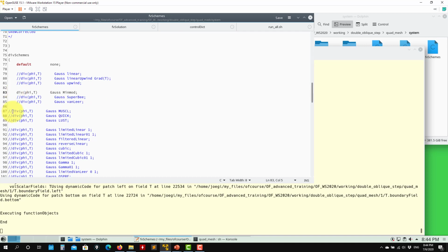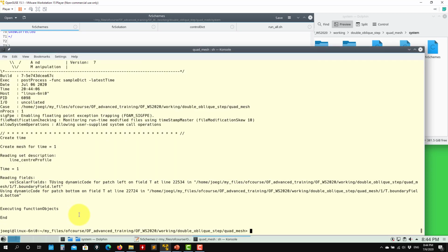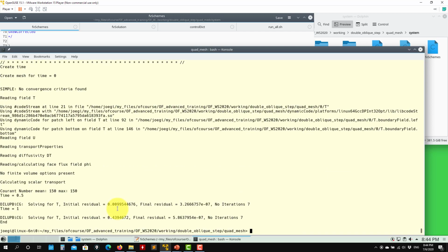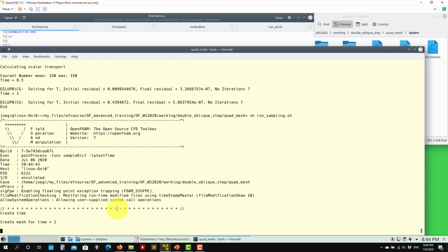So let's check here the MUSCL scheme. This is a very interesting method because actually it starts second order accurate. So this is one that extra accuracy you can go. But again, don't use these methods. It's very rarely when these kind of methods are used. Okay, so for production runs just stay with linear upwind and a good TVD scheme like the min-mod or Van Leer.